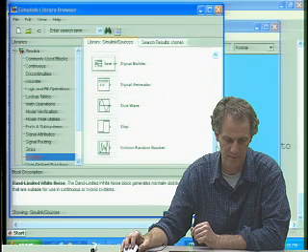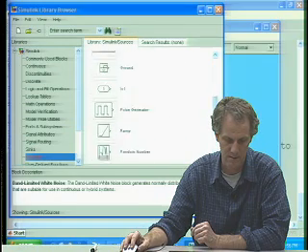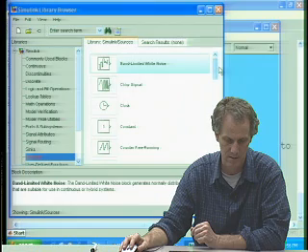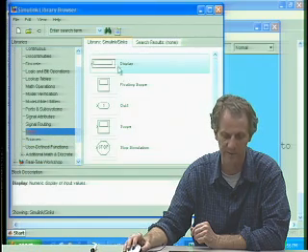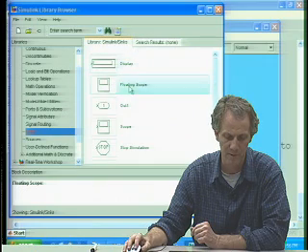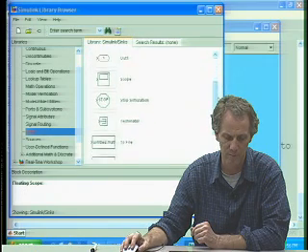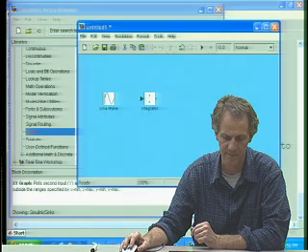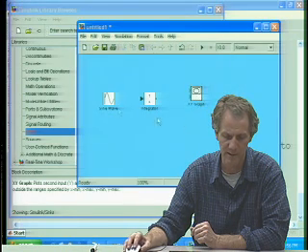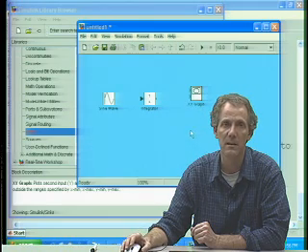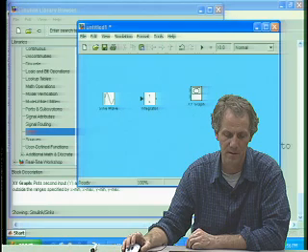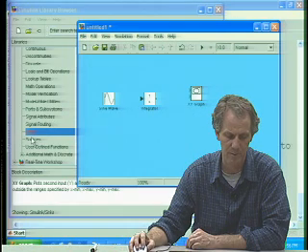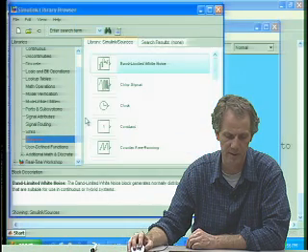Plot, I think. Where did it go? Oh, I'm under source. I'm supposed to be in sinks. There we go. Under sinks, there's different plots. There's scope, but what I want actually is XY graph. So I'm under sinks, XY graph. Now I don't want the integration of the sine wave to be my x value. I want it to be the y value. What I want for the x value is time, so I needed the clock.